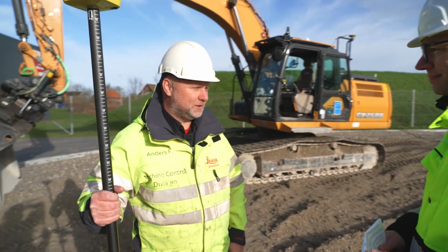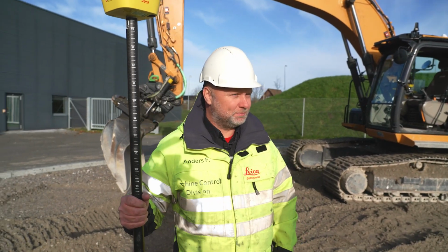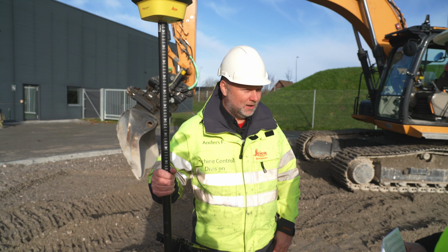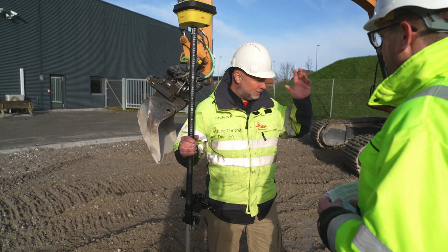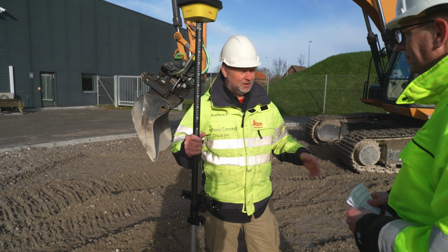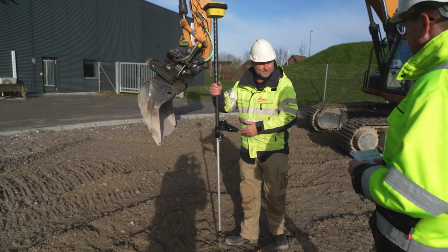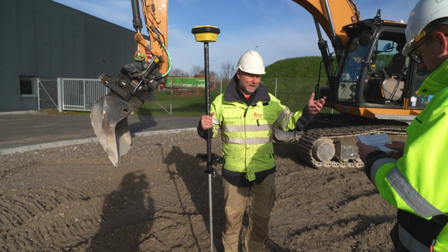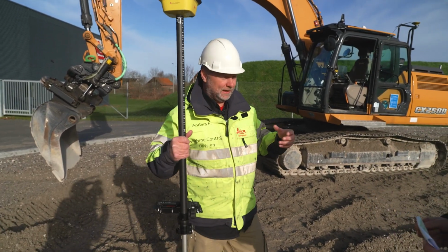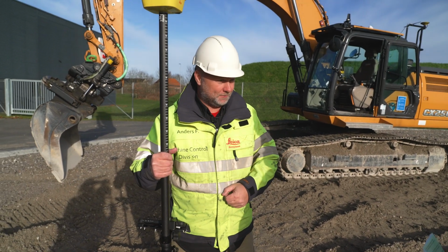As-built data is something you receive when you collect information about something that has been made or has been built. Quite often you do it with a rover. So basically when a certain task has been done, you show up with your rover, you measure a couple of points to verify, and that is then brought into the office, and you bring it into your office software and you create some kind of design out of that based on your measurements.